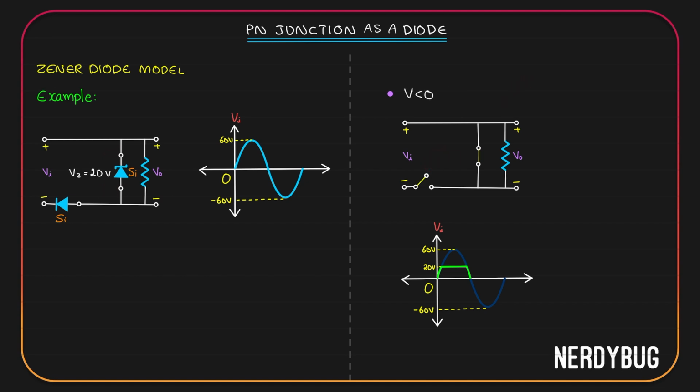Normal diode is an open circuit, Zener diode is a closed circuit. One thing is we are taking the output across a closed circuit. There is no potential drop anywhere, so the output is going to be 0. Or you can think like this. This is opened, so no current is going to flow through the circuit. So the output voltage is 0. Let us plot it on the graph like this.